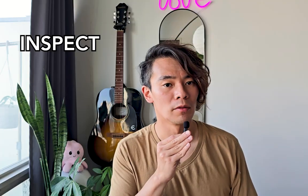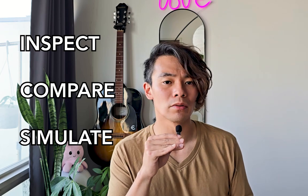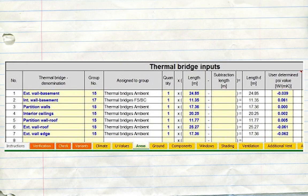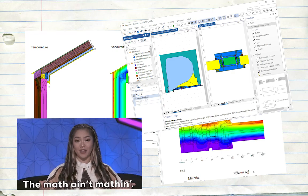Here are the 3 steps to hit passive house level. Inspect visually, then verify with a thermal image or a probe. Compare your detail to those in the passive house catalog. Simulate using tools like Flixo, which Passive House also offers a course for. The PHPP software applies correction factors for construction quirks, but note these do not always impact in a negative way. Just note, constructional bridging only works with 2D simulations. Your well-known formulas sometimes won't cut it.